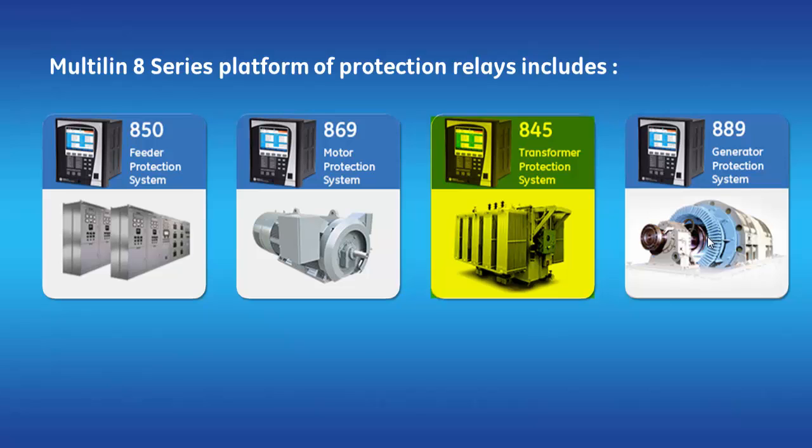845 has been designed for protection, control, and management of 2 and 3 winding power and distribution transformers in both utility and industrial applications. 845 provides advanced functionality for a wide range of transformer applications, delivering high-speed protection and advanced transformer monitoring and diagnostics, like hottest spot, aging, and loss of life.